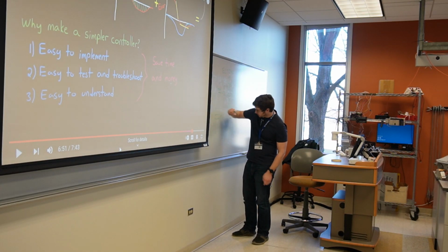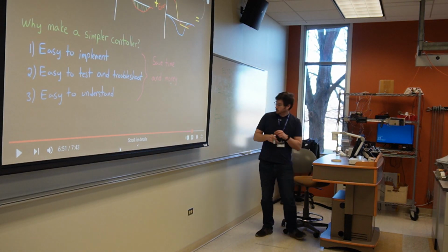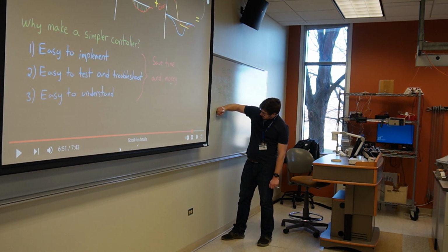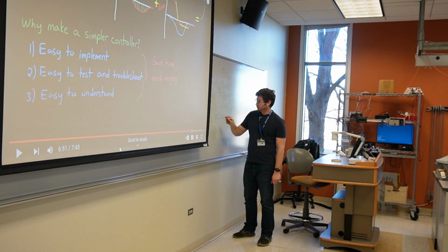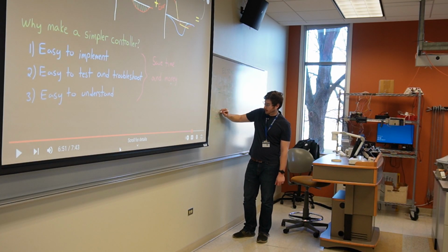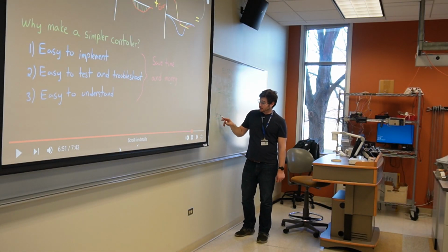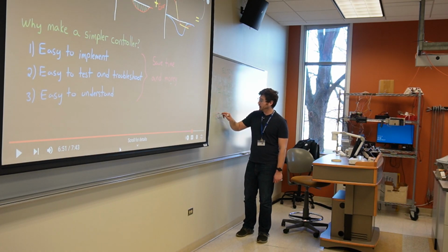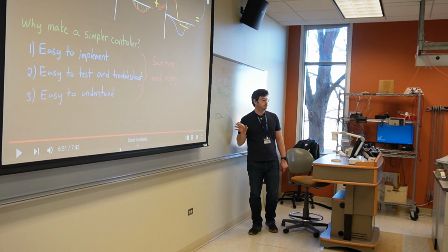If our error, which I'm going to draw in red, starts here because we just added here, and then we add it more, and more, and more. After some amount of time t, we now have a large command signal, that's this line, that says, hey, I'm commanding firmly for the motor to make up this difference, for you to push a little bit harder. This line would drift up, the error would go back to 0 or drift down towards 0, and then the I term would calm down again. It says, okay, I'm happy where we are, you don't need to change.